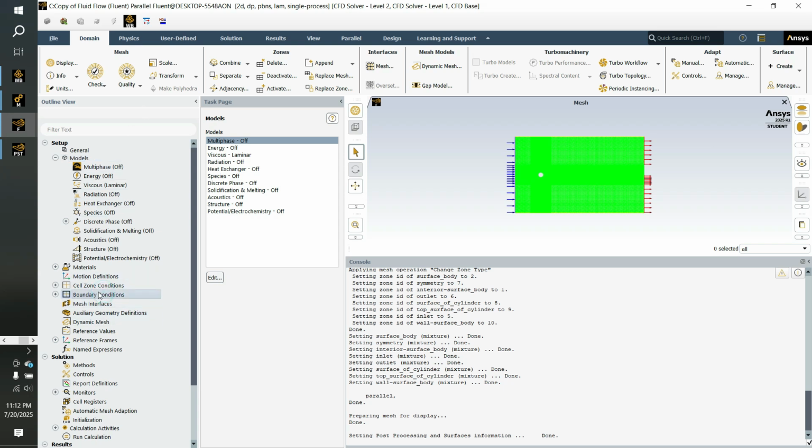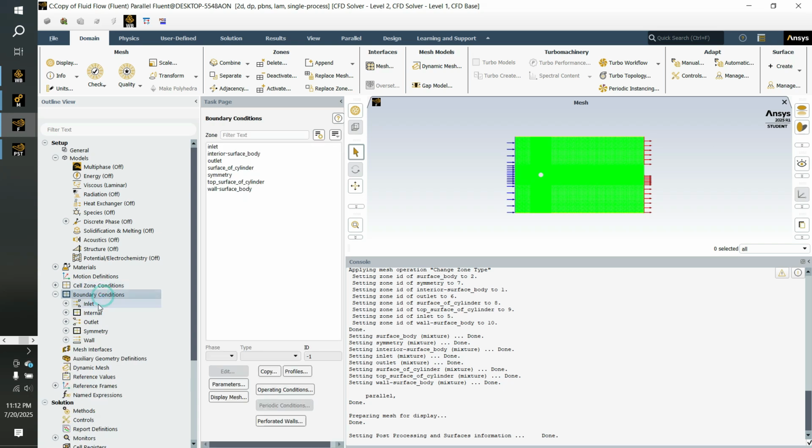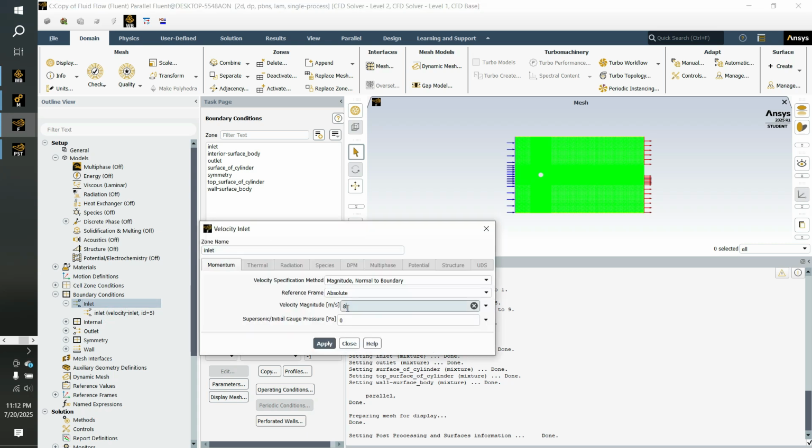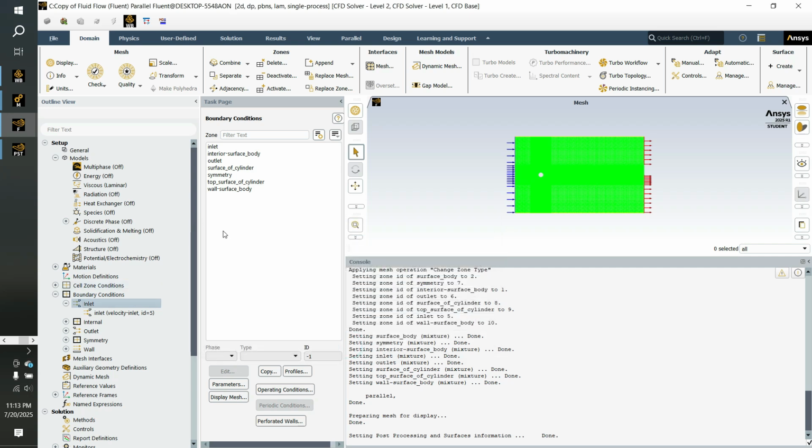So I will change boundary conditions of the inlet to, instead of being 8 meters per second like the turbulent, 4 meters per second like the laminar, I will try 0.05 meters per second. So again, that will bring the Reynolds number down, creating an almost zero drag coefficient.